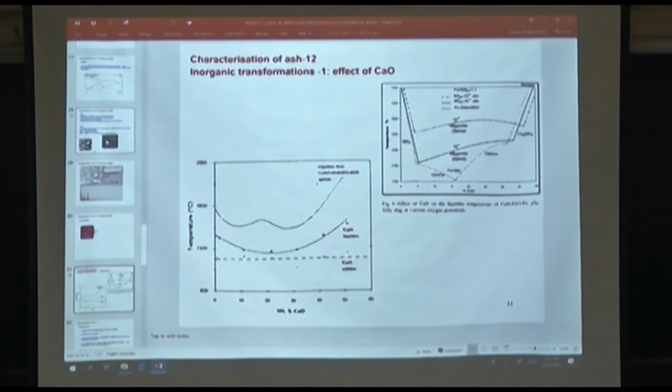You take the samples out. You don't know why exactly it has created that problem. Roughly, you know that, yeah, maybe I have gone to too high a temperature, but what exactly has happened? Take the sample out, analyze it by EDX, get the composition, put it into the software, and develop this sort of graphs.